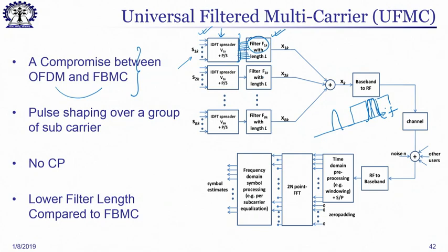That is a requirement, and these different waveforms have the capability to do it. Complexity is an issue. So UFMC, what we said earlier, is one which compromises between them, provides the facility to sneak in a small section of bandwidth, yet have low out of band leakage and have complexity comparable with OFDM and much lower than that of FBMC.